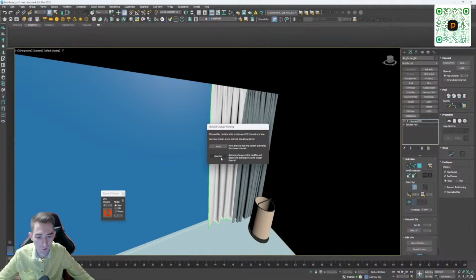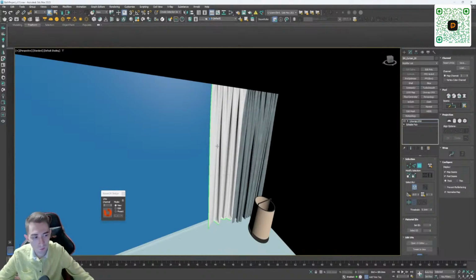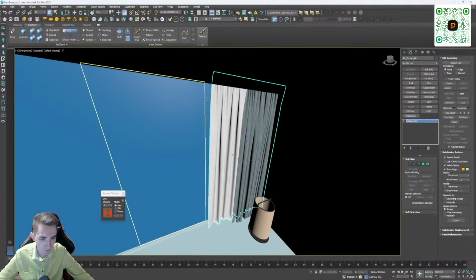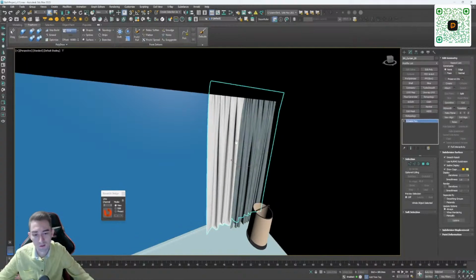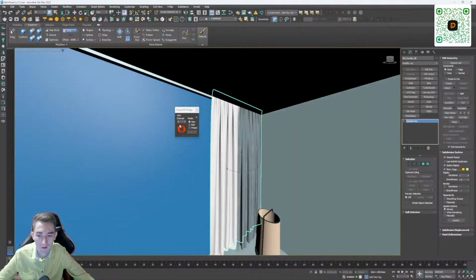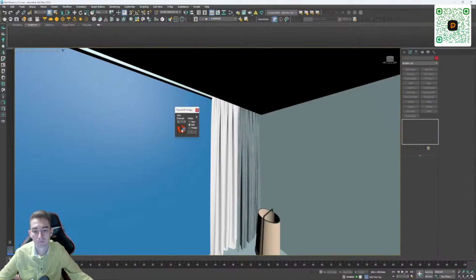And if we had pressed OK, we would have just moved on. And we need to copy it. Press OK. Now convert to Edit Poly. Usually I collapse modifiers, so in principle, the rise does not fail. If you do not collapse, it happens that some kind of failures occur. Now we are not creating a new one, that is, we are not choosing New here, but choosing Edit, that is, changing the scan. Select the second channel here as well, and go to Pack.